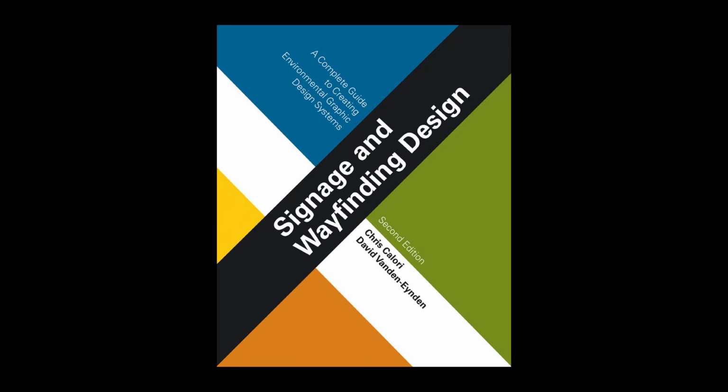All wood products can be painted or clear-coated and can take a range of surface textures from smooth to highly textured. Typically, the more lowly and unattractive the wood product, such as medium density fiberboard, MDF, the more likely it is to be used simply as a substrate panel, to be covered up with paint and graphics.